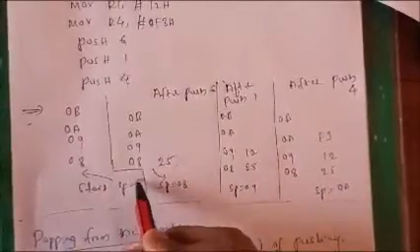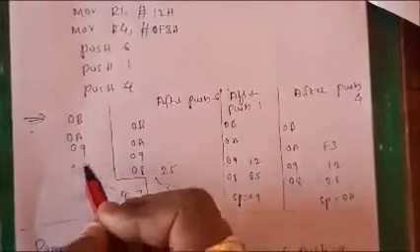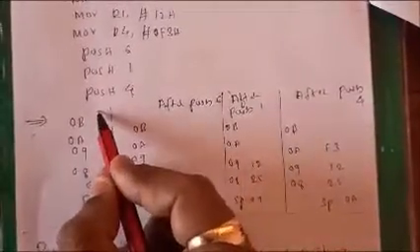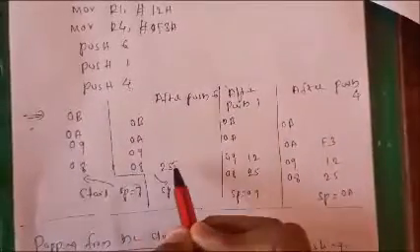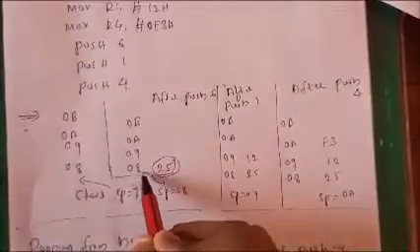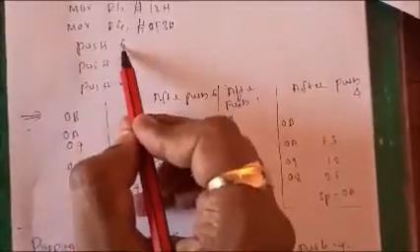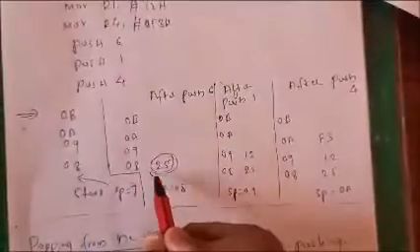Stack means what will happen? Already I said the default case is 07, so the next byte address is 08. From this address onward it is going to store the data. So after push 6, 08 is going to hold the value of 25. Why is it 25 here? I am performing push 6, and 6 means R6. What is the content? 25. So that means you are going to store 25.